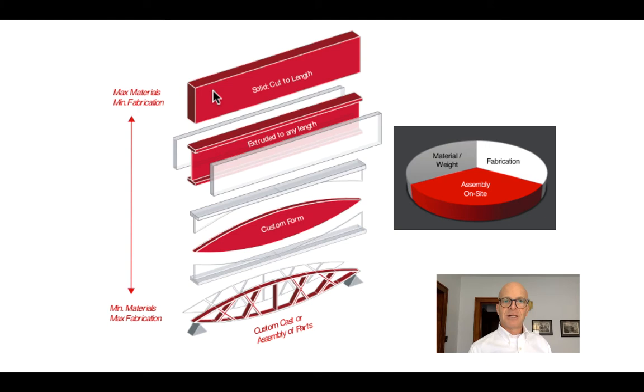If you look at the solid section versus the kind of hacked together shape, what you see is that we don't have as much material, and therefore the beam doesn't have to carry as much of itself over the span. Remember when we were doing beam design, we kept having to go back and throw the dead weight of the beam into the equation, and very often that meant that the beam couldn't actually carry the load that we wanted it to over the distance.